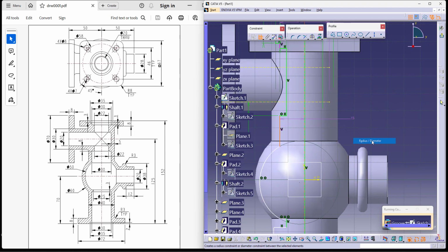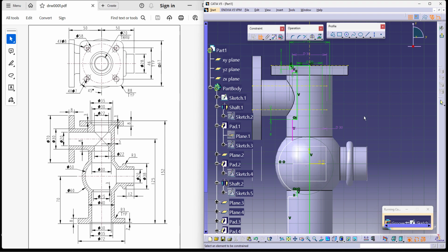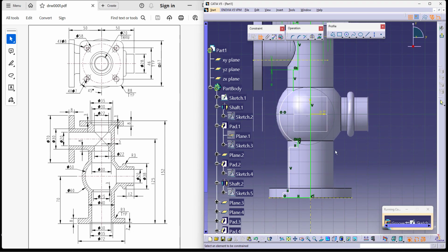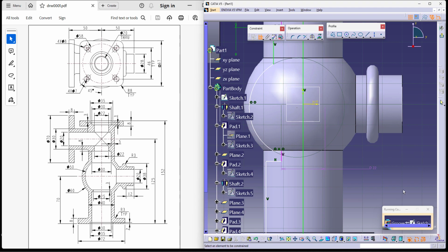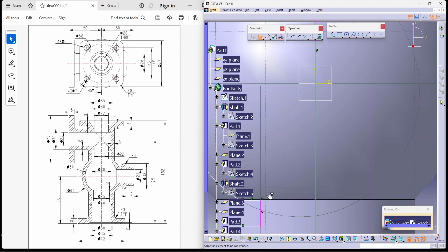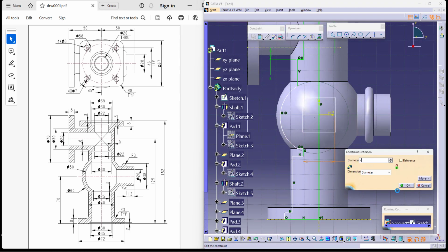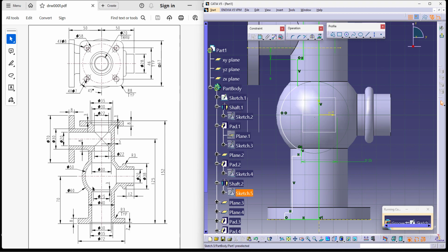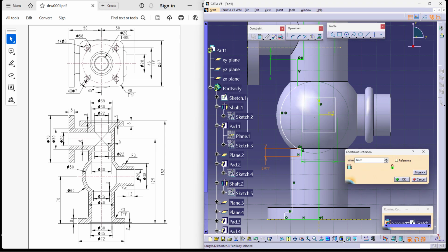I need the axis, so I'm just going down. It's already by default 30, so I'm not troubling it much. I think I have constrained it at the top. Now, this dimension again should be constrained. This is not in line with anything. This is supposed to be 25. So let me delete the constraint, whatever is keeping it in line, and give this 25. This depth is again 3. So let's give this as 3. I'm going one after the other.